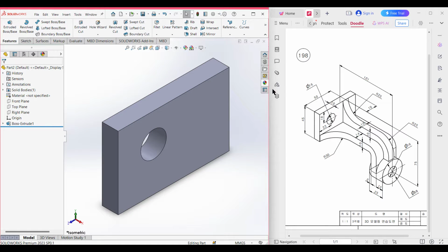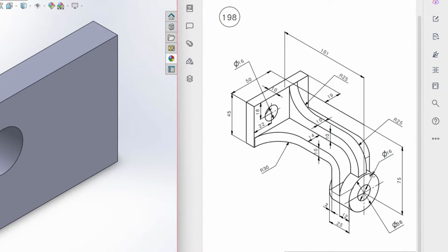Let's go back to our sketch again. In our sketch, we can see that we have a circle here, and this circle has a dimension of 38 diameter. For drawing this circle, we can see that from this surface to this circle, it has a distance of 101 unit. So first of all, from this surface, I will draw a reference plane of 101 unit apart from this surface, and from that reference plane I will set the sketch and draw a 38 diameter circle.